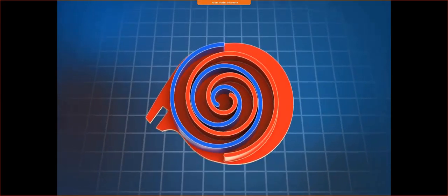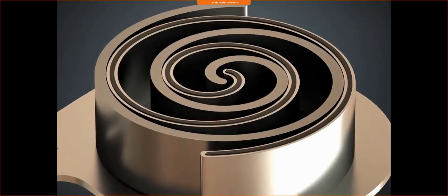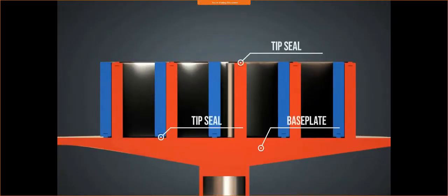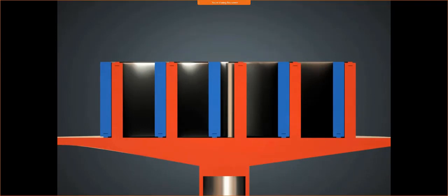Today, there are several compressor designs. On the one hand, the movable scroll can move with an extremely small distance to the other scroll. The scrolls therefore do not touch each other. On the other hand, there are also designs in which the scrolls are in contact. Such scroll compressors usually have a better seal, and thus a higher efficiency. Axial sealing can also be designed in various ways. One possibility is the use of a floating tip seal. These are present on both scrolls and are pressed against the base plates by gas pressure. In this animation, the upper base plate is not shown.